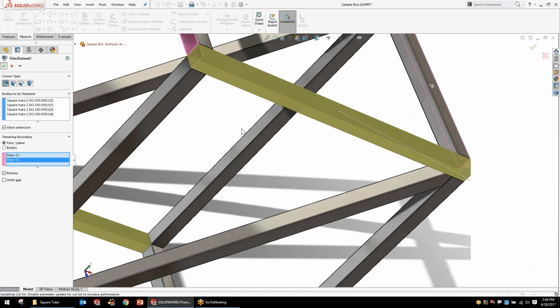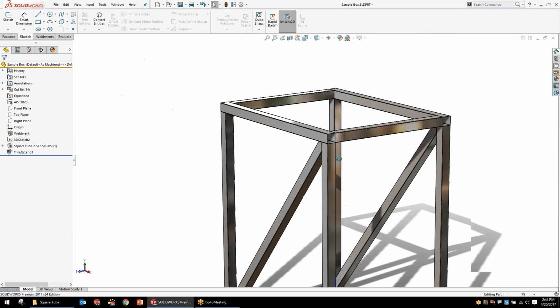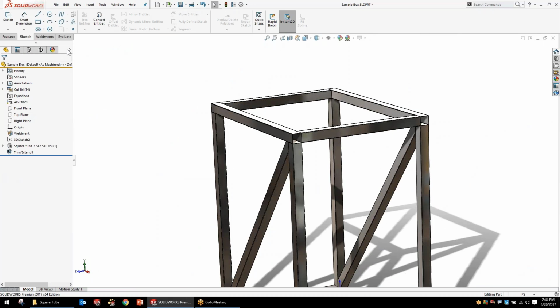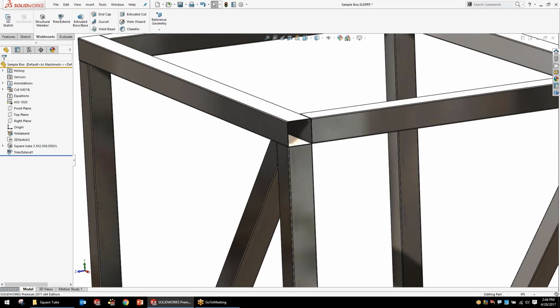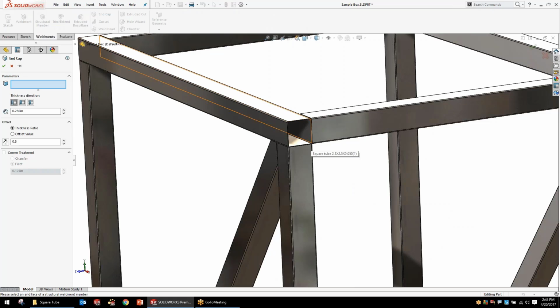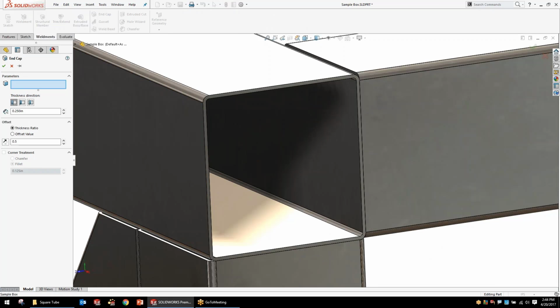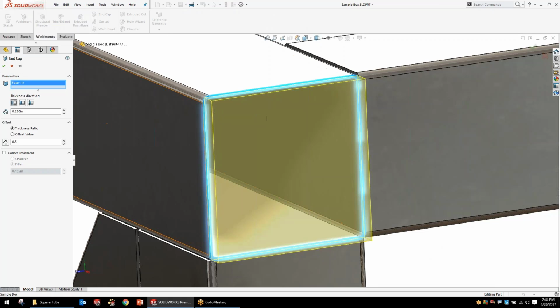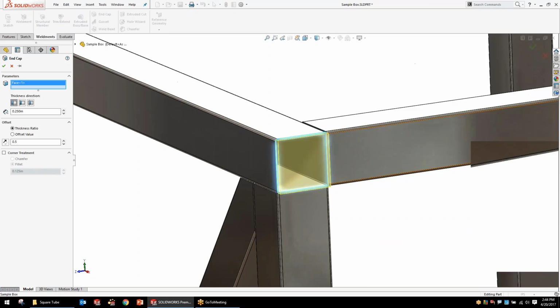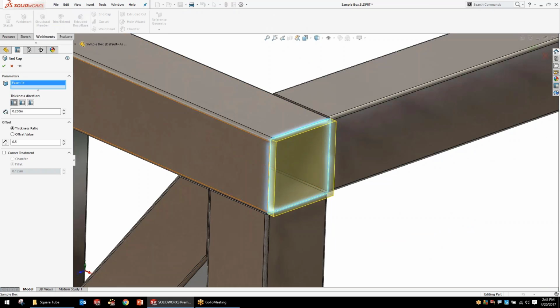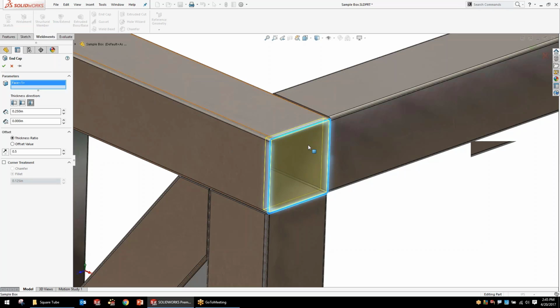I can real quick show y'all, there's a few other quick, easy tools for Weldments. Say you need to put end caps in your part, it's pretty easy. You just use the end cap tool from the Weldments tab and select the face that you're referencing off of, that you're capping, and you can set it to be offset on the end, inset, and it will trim the Weldments tube for us, or inset and within the tube.